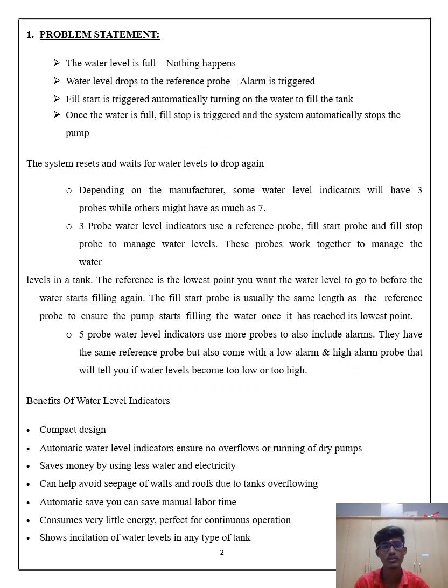Problem statement: the water level is full, nothing happens. Water level drops to reference probe, alarm is triggered. Fill start is triggered, automatically turning on the pump to fill the tank. Once the water is full, fill stop is triggered and the system automatically stops the pump. The system resets and waits for the water level to drop again.